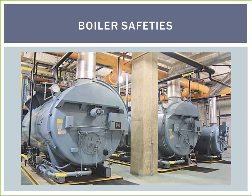There are numerous safety features to prevent failures in boilers. Safety valves release steam before a dangerous pressure can be built up. Fusible plugs over the firebox melt at a temperature lower than that of the firebox plates, thereby warning the operators by the noisy escape of steam if the water level is too low to cool the firebox crown safely.